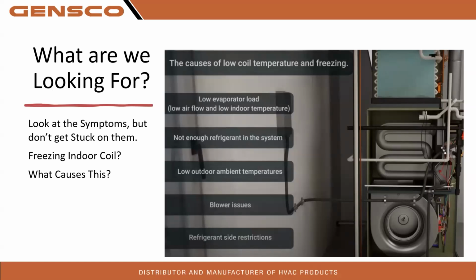Maybe we don't have enough refrigerant in the system. We don't have enough refrigerant flow. We're out of refrigerant. It's going to start flashing off and boiling whatever's in that coil, and it ain't coming out because there's no way to pump it. Maybe we have low outdoor ambient temperatures. Maybe because we don't have enough outdoor temp to expel and condense that liquid, maybe we should have a low ambient kit. Maybe our blower's having issues. Maybe we have the wrong universal blower, wrong capacitor. Maybe it's not set up right. Maybe we have some refrigerant restrictions.